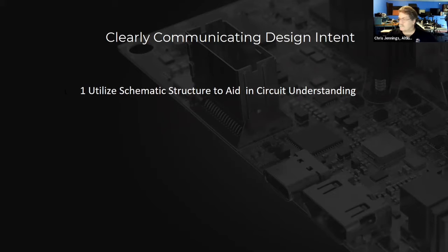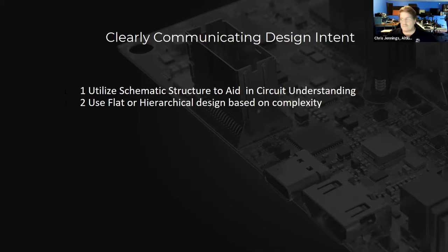Let's see. So again, you want to make sure that you have your schematic structured so that it's easy to understand the flow. Let's see, looking at the project, yeah, we talked about the project overall. We talked about hierarchical. Okay, just making sure we got all the stuff based. Again, use flat or hierarchical design based on the complexity. Don't make it more complex than it has to be. But a lot of times having hierarchy, even in some of the simpler designs, can demonstrate more cleanly data flow, for example. That's important to understand.